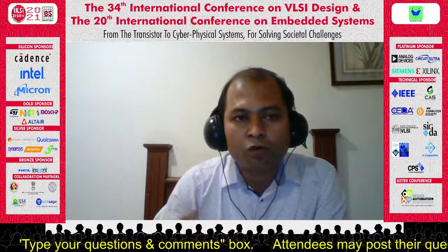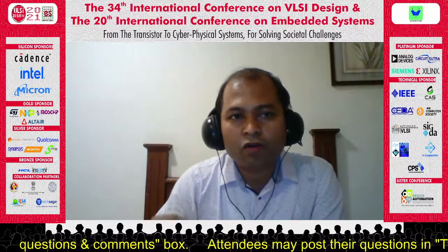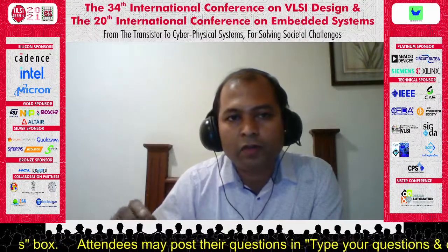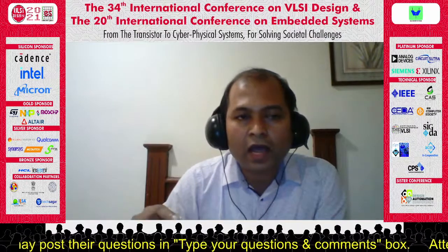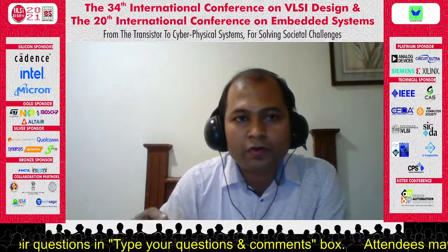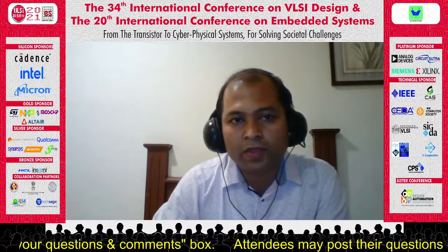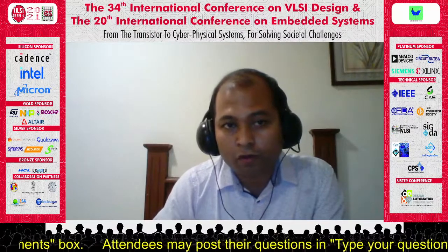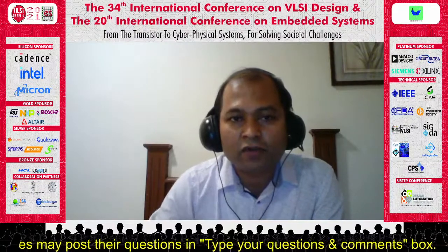Now, for the AND gate, from the logic of probability, if we take the conjunction, then with the two input probabilities P1 and P2, the output probability should be P1 into P2. For the OR, that is for the union operation, the output probability must be P1 plus P2 minus P1 P2. So basically, the union operation is taken for the OR, and the intersection operation is taken for the AND gate, and in this way the probabilities are calculated.